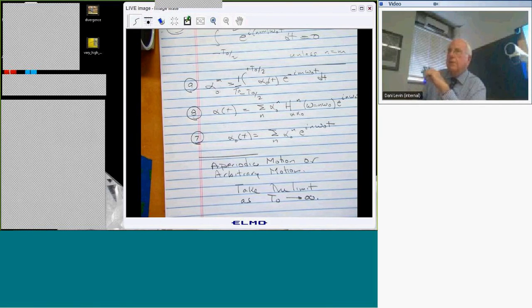When they do gust response in Israel, do you use power spectral density? You use, okay, fine, good. So people really use it then. I mean, in the not too distant past, people sort of avoided the power spectral density formulation because you can do gust analysis another way. But probably the most rational way to do gust analysis is using the idea of random inputs and random outputs, and that's what many good organizations do, the ones in Israel.